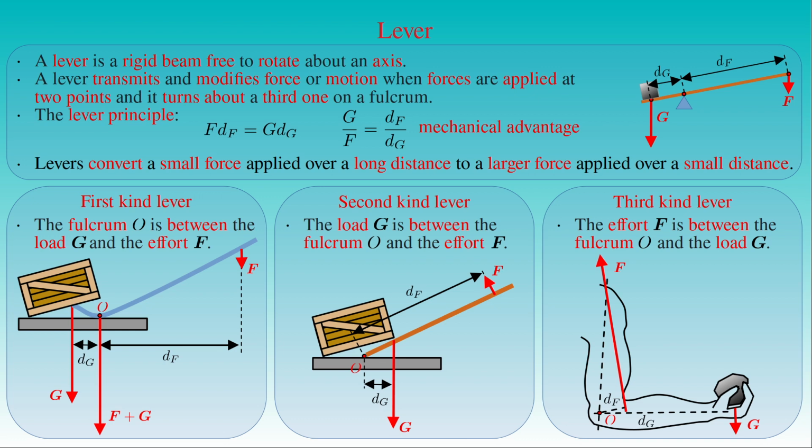In the example illustrating second-order levers, the axis O of rotation is fixed, that is, the fulcrum is always at the end of the beam on the ground. In the case of the first-order lever shown here, the position of the axis of rotation changes along the curved crowbar with rising or lowering the right end of the crowbar. However, we can always replace the instantaneous axis of rotation with a fixed imaginary axis at a given instant of time, and determine the condition of equilibrium of the lever.